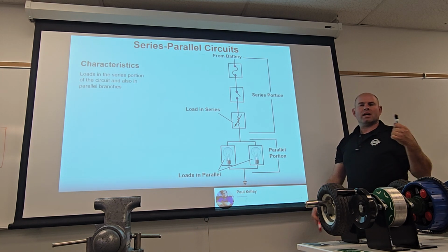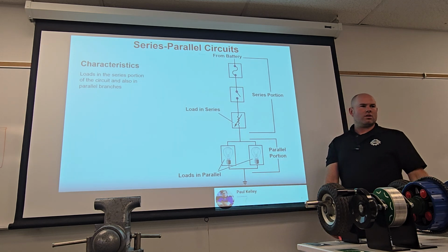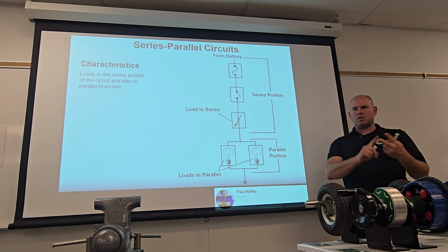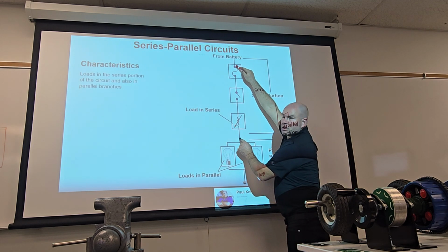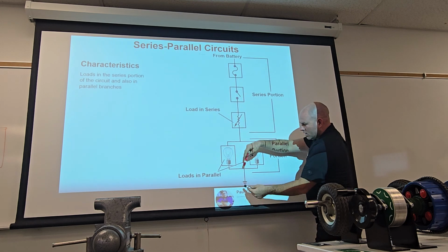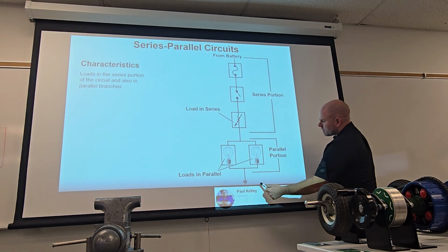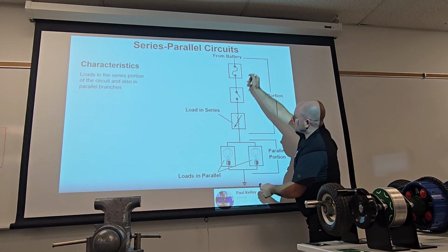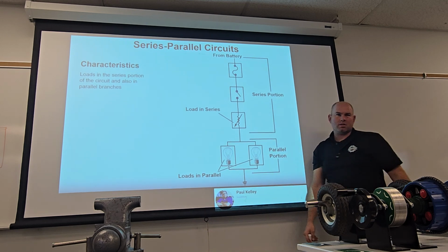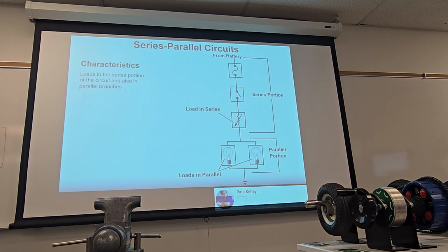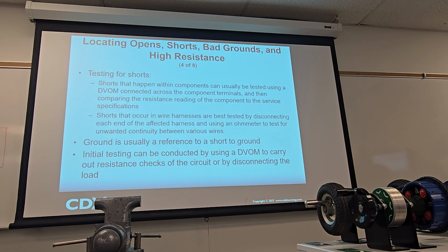So I like available. Available tells me a lot, but sometimes the service manual is more like voltage drop it. And you'd be like, all right, whatever. You got to be totally bilingual. Available voltage and voltage drop. I could flip them one way or the other. 0 voltage drop, this circuit's good. 12 voltage drop, this circuit's bad. Do it in available voltage. I have 12 volts, this circuit's good. I have 12 volts, this circuit's bad. Makes sense? So that's kind of what that's saying. And how'd you know that? Well, you're understanding all the laws of electricity and how to apply them, right?